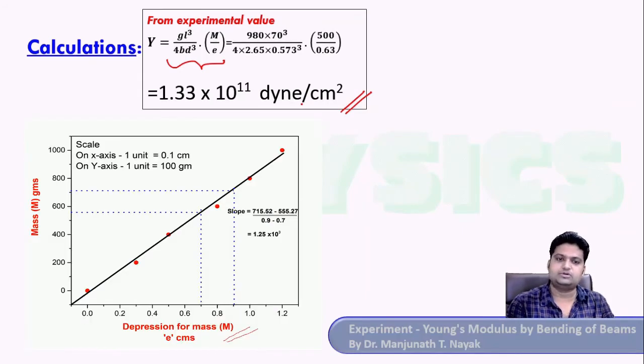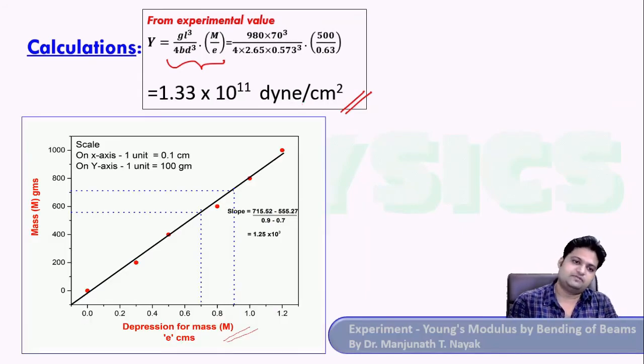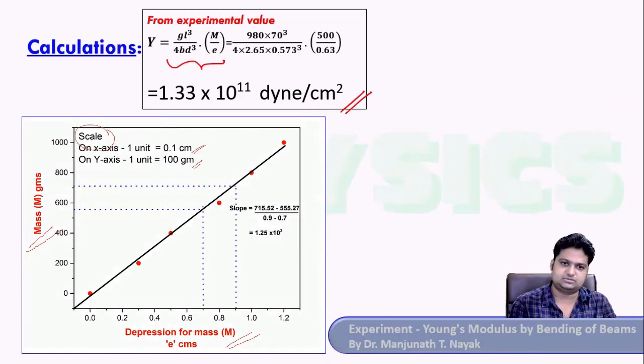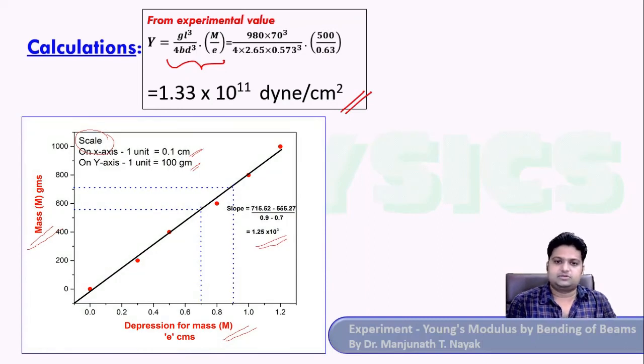Next, what you could do is plot a graph of the values that you got from the depression of the beam and the masses. You'll get a graph like this. Remember the scale. To write your scale, 1 unit I have taken as 100 grams. You can take what you want, your preference. 1 unit is 0.1 centimeter of depression I took. Find the slope. I got the slope as 1.55 into 10 raised to 3, and see that the graph you draw in your journal contains all this, as in the graph image that I've shown you.